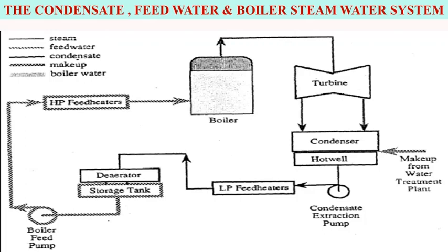So these are all parts, and there is makeup water also and the condenser also, which constitute part of the feed water. The makeup and condensate are mixed ahead of the deaerator and pass through the deaeration system, then go to the storage tank, the boiler feed tank, from where water is fed into the boiler feed pump, and there may be a booster pump, and from the BFP discharge through HP heaters it goes to the boiler again.